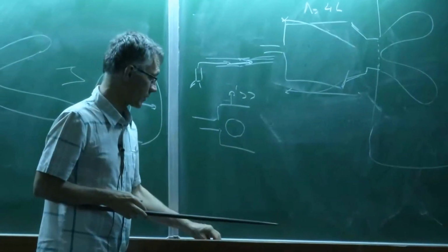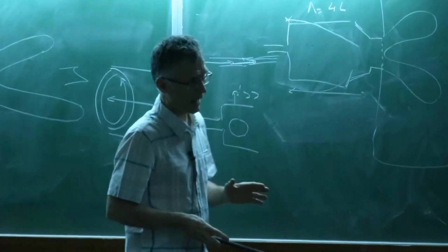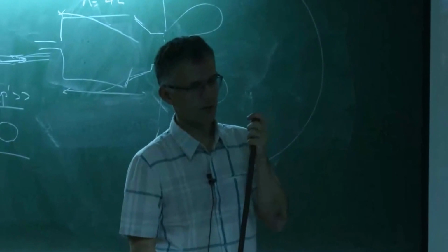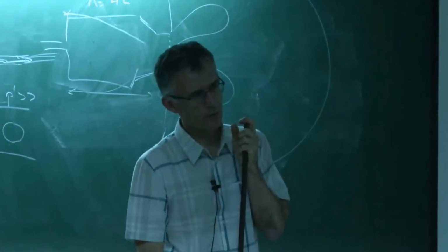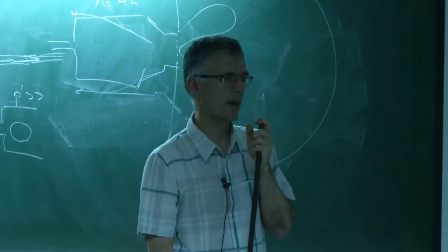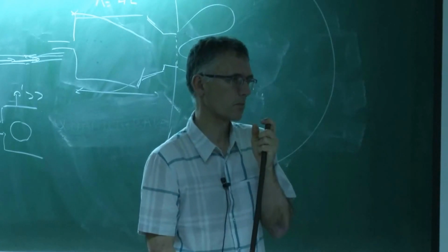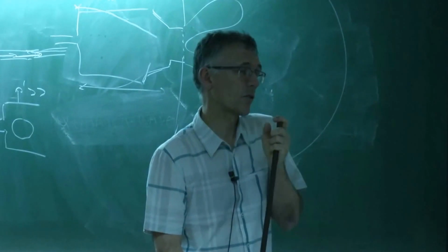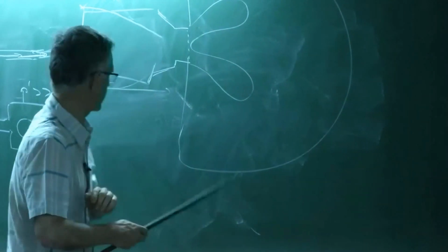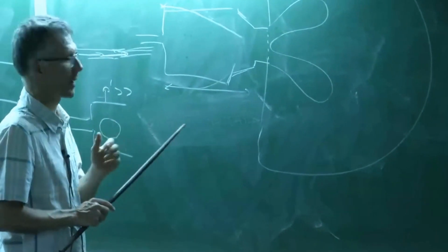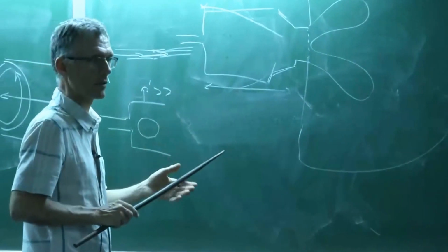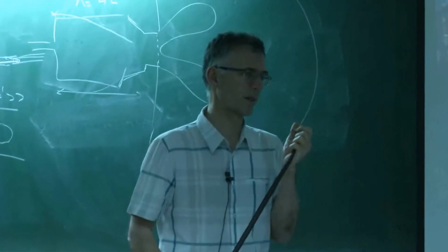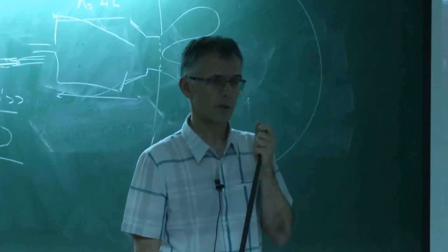So what you say is absolutely true. Today we predict the frequency with very good precision. If you want to know the amplitude, I would say that if you get the amplitude within 30%, it's good, because it depends on many phenomena. Also sometimes in the experiment there were liners that they didn't tell you there were liners, so the liners are also damping the whole thing. 20-30% accuracy should be expected, which is not that bad.